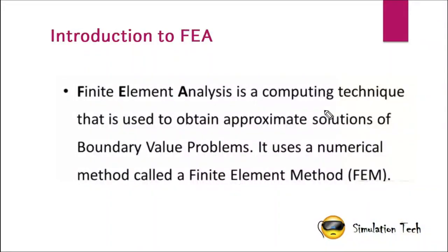Okay, so let's get into the topic. What is FEA? You already know about FEA. In our previous session we have already seen a little bit about FEA, and FEA is a computational technique that is used to obtain an approximate solution of boundary value problems. It's a numerical method called the finite element method, or else we can say finite element analysis. It's one type of numerical method. We have four types: FEA, FEM, FDM, and another one is the boundary element method.